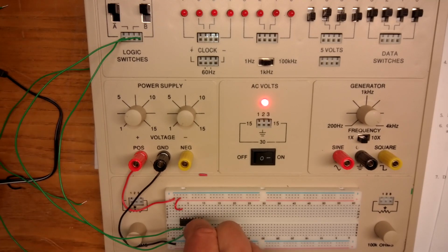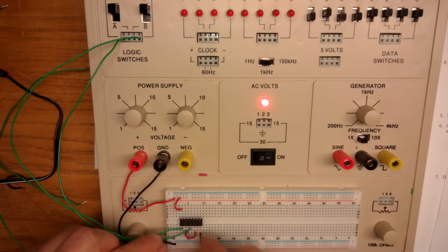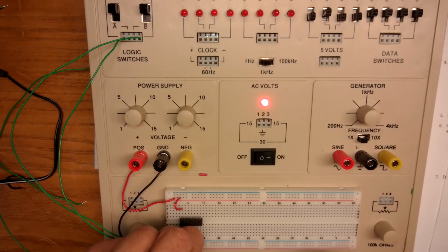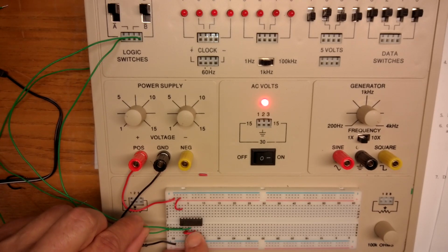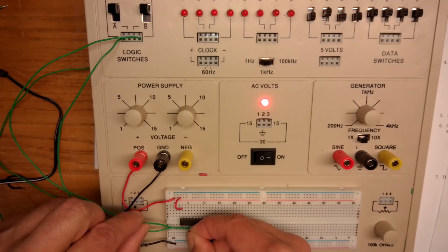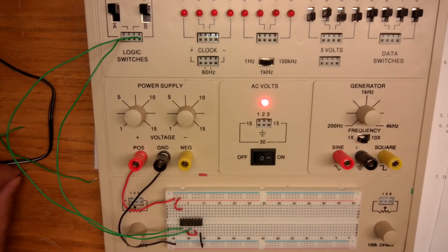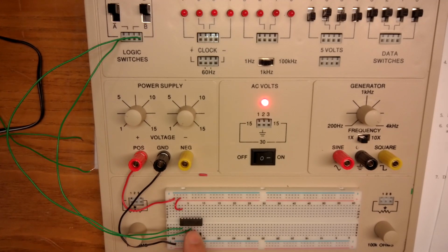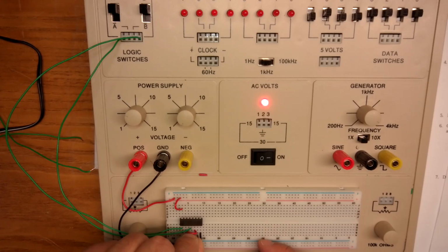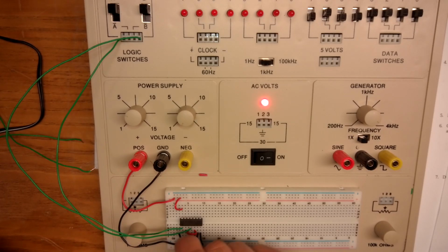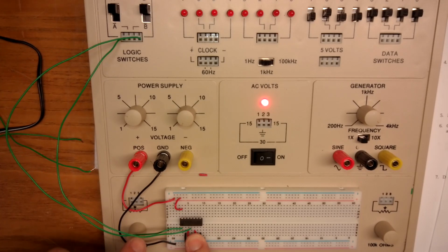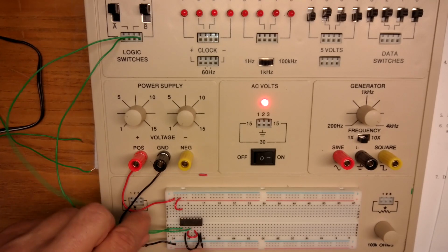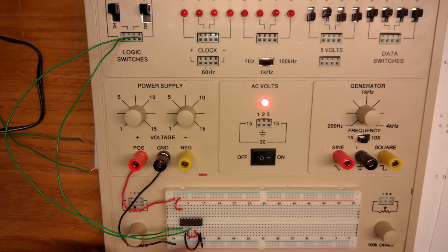And I would note, if you're curious, it doesn't really matter which input I use for the S part coming in, which one I use for feedback. They just have to be the opposite. So I took my output of the first one, and it's the input of my second. Likewise, my output of the second NAND gate, which is all the way over here, pin 6, has to go back into pin 2, the unused input. So you can see there, I have 2 inputs here in the feedback, 2 inputs here in the feedback.